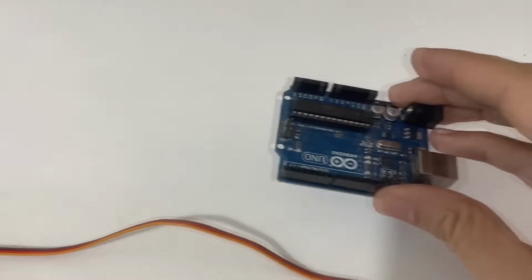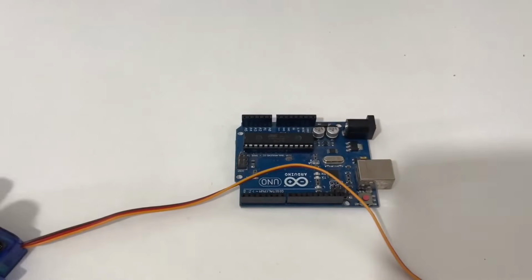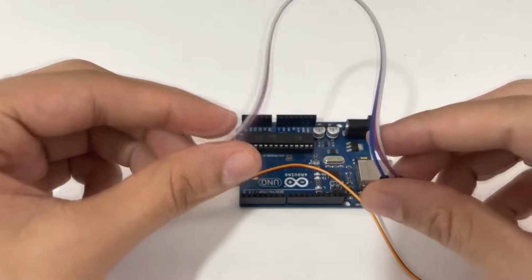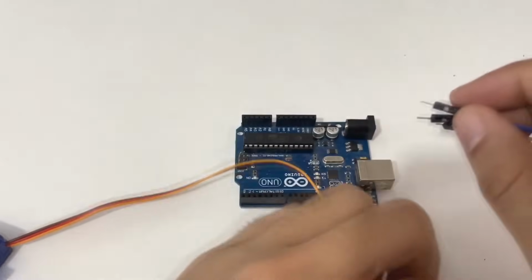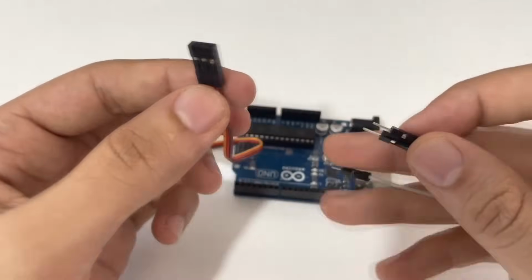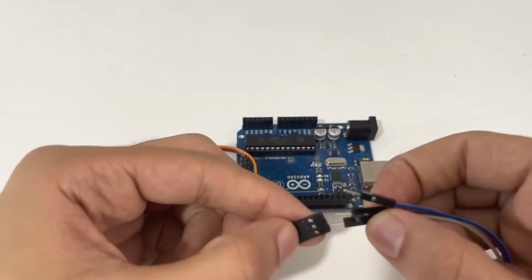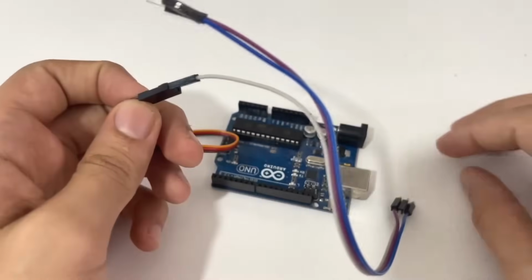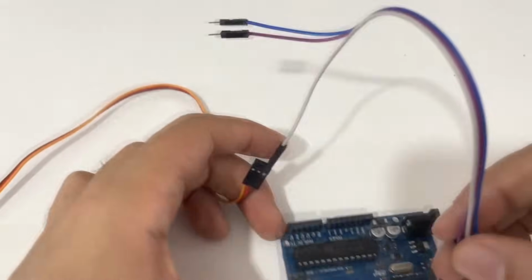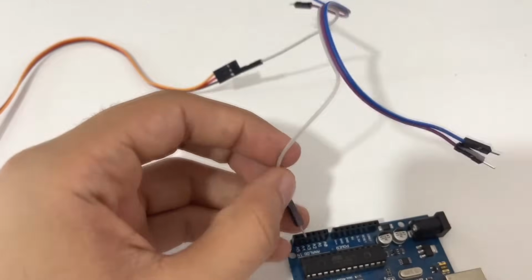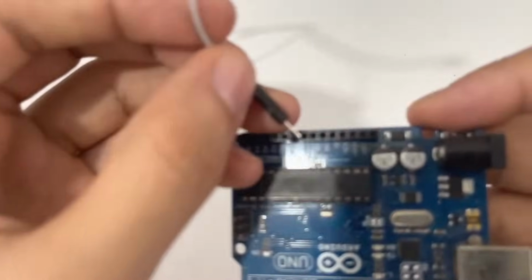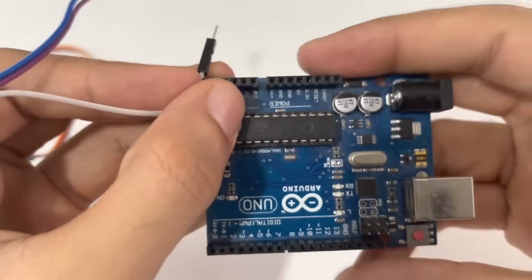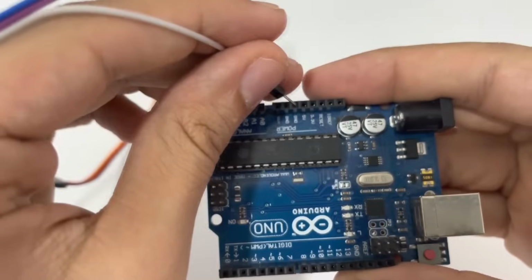Alright, so here is our Arduino, and also we need some cable for connections between Arduino and servo motor, and let's do this operation now. So first let's start with our brown cable, and as you remember, the brown line is representing our ground line. So let's wiring to the ground. So you see here, let's focus this now. Alright, so let's select the ground,